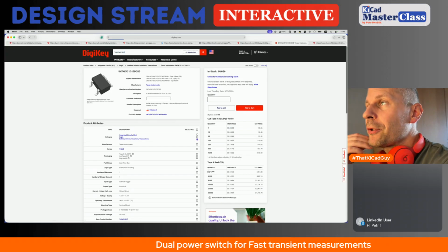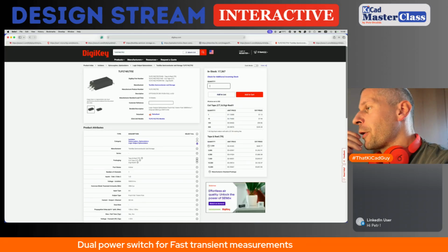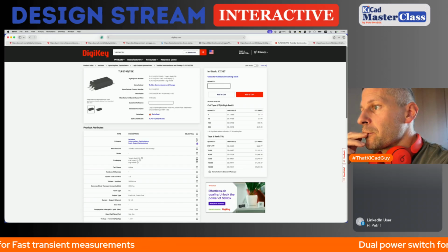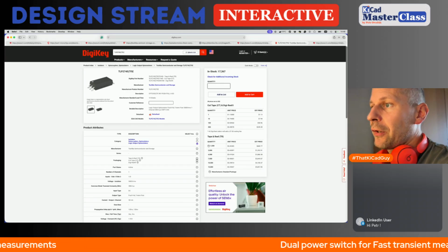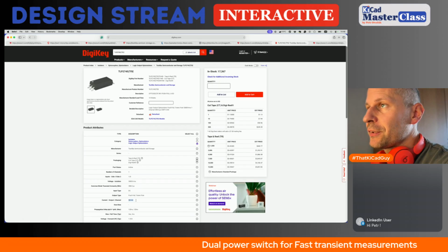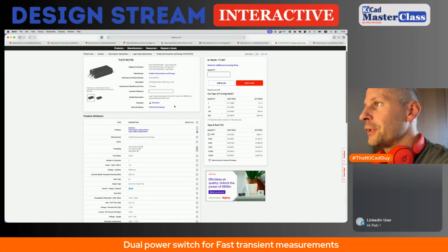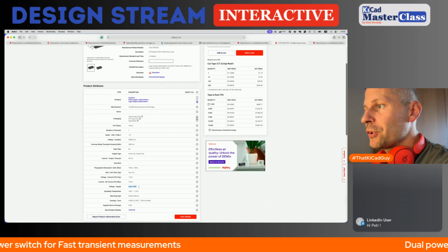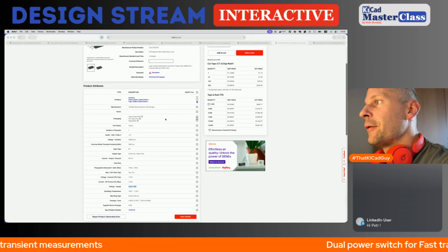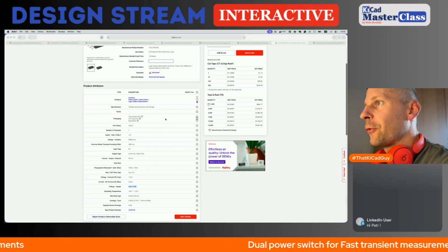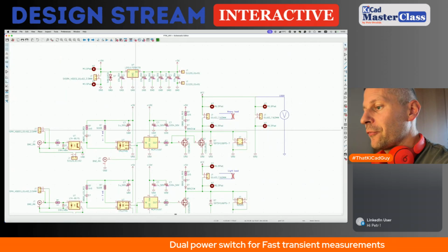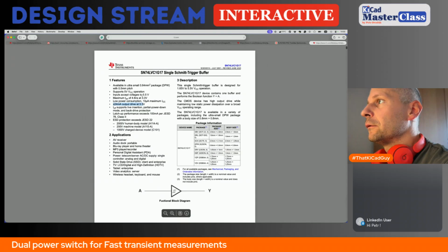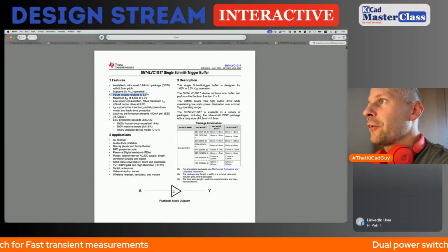And here is this digital output optocoupler, and the price is 3 times higher. Output current is 50 milliamps, which is not needed. Here we are driving the gate driver only. The voltage range is up to 30, but we drive it from 5 volts, and the LVC accepts 5.5.